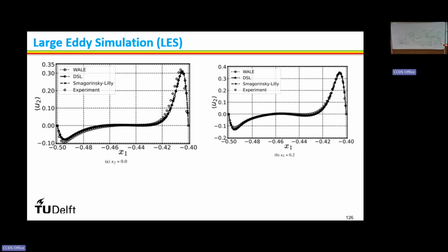Professor Rajaram was discussing yesterday doing LES for some geophysical flow, but not in physical space. They transform the Navier-Stokes equation into the spectral plane and solve it. They are solving the convolution operator, the interaction among eddies, in spectral space, right? And some other professors, like Professor Tapan Sengupta from IIT Kanpur, solve the implicit LES. They don't explicitly assume any subgrid scale model, right? They are using very high order, fourth order or sixth order numerical schemes, right?